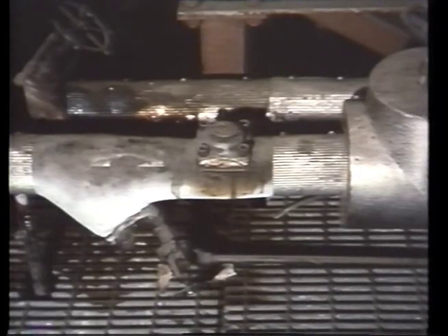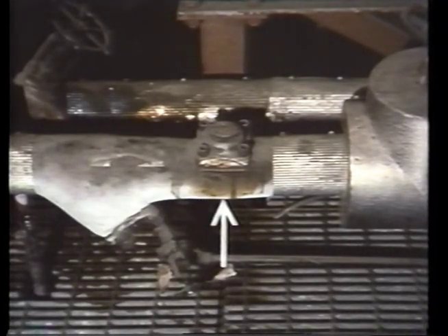Unlike thermostatic traps, thermodynamic traps can and sometimes should be insulated. Now, if you have any doubt about the characteristics of a particular trap, read the manufacturer's literature on that trap. Manufacturers often provide all the information you need to know in order to properly maintain the traps in your plant.